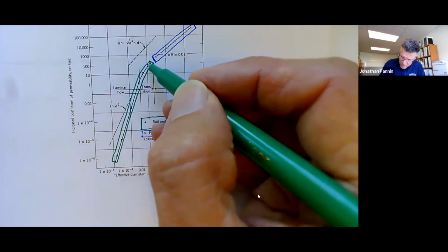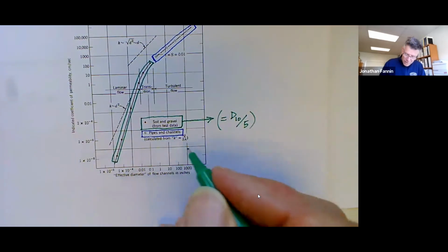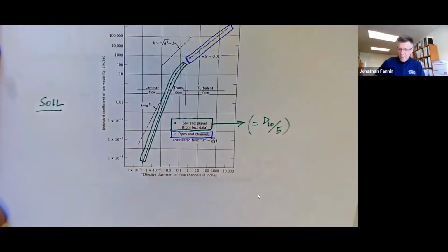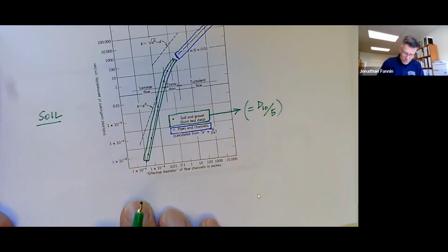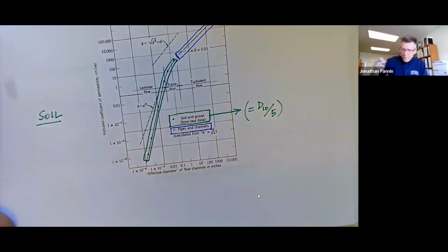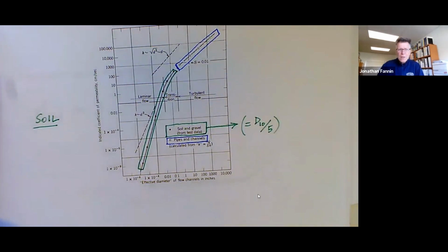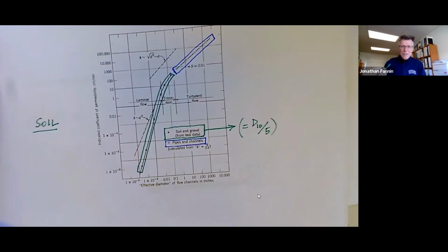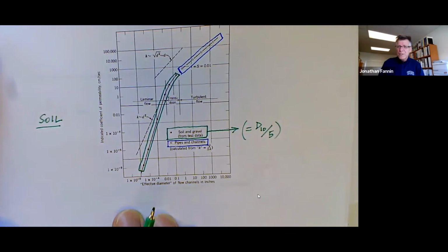We'll hold for the moment on the little curvature that happens up here. Let's observe that for the soils, right? We have Darcy's law, V proportional to I, and there are empirical relations between permeability and, for example, D10, Hazen's empirical rule, or a much richer one, Kozeny-Carman's empirical rule.